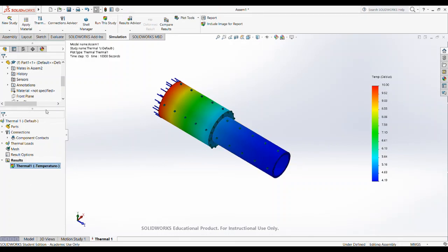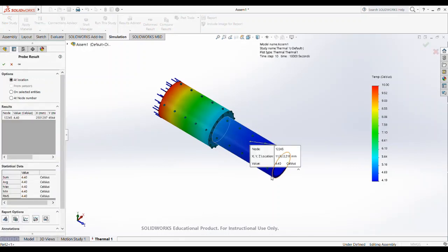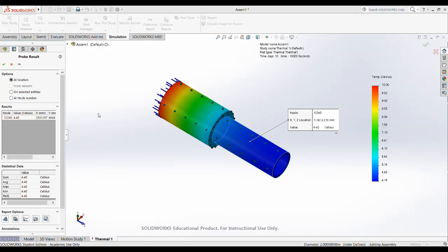You can right click, probe, click in the middle somewhere, and just map that out. All right, so now we've got a better distribution, something I'm more comfortable with. You can screen capture this if you want, but a cleaner way of doing this is to save this as a CSV file: file, save as, and then you would just graph response 1. I'm going to hit return, save. It already exists, so replace it. Now I can go back into my directory and pull out an Excel readable CSV file and just plot it out, and I can put in axes.